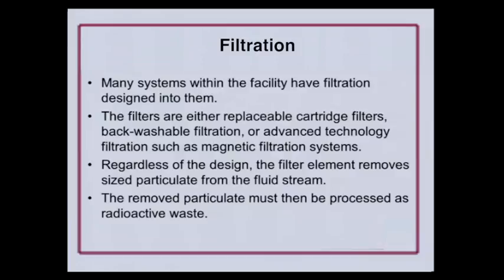There is technology out there that has that. There's also some advanced technology filtration, such as magnetic filtration systems. That works really good. It's a combination of magnetic as well as backwashable, but it only applies if it's ferrous material. If you have non-ferrous material, which some of the alloys used in the plant are, then it's not very effective.